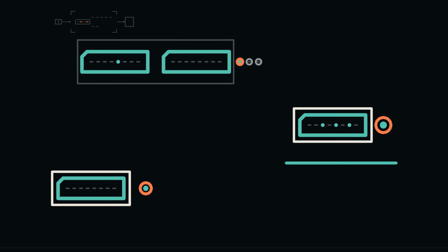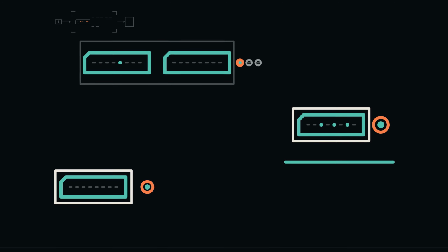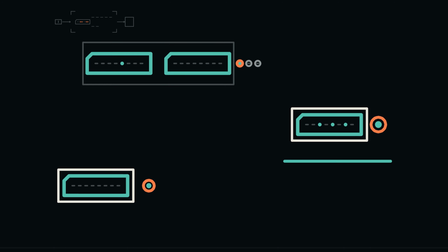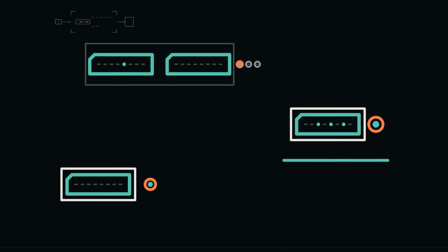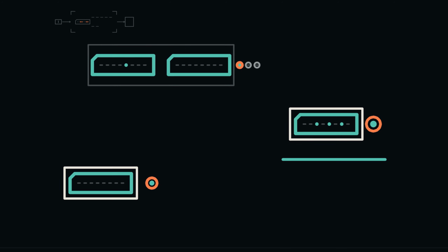Halt still performs the full 6 edge fetch. Its execute edge sets the halt latch and enters halted. R0 remains 0. Flags are preserved. No later clock edge performs another instruction.